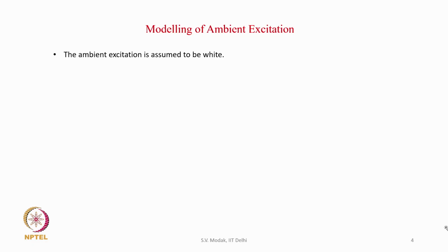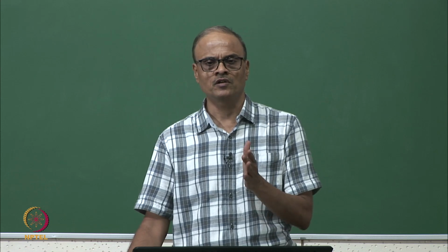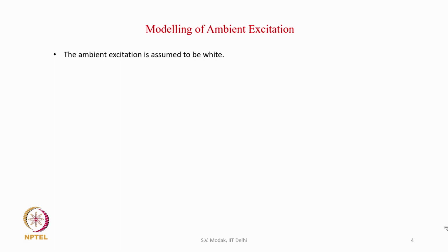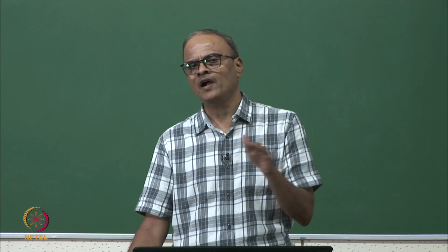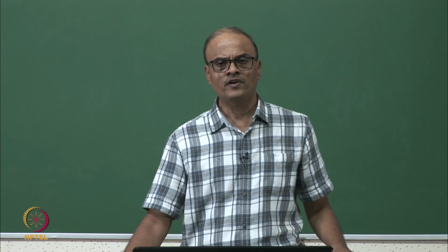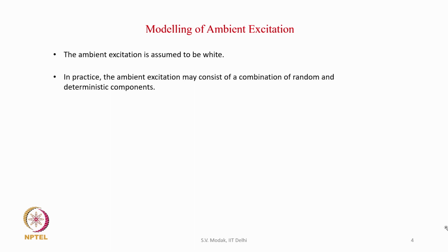The ambient excitation is assumed to be white in operational analysis. So, operational analysis assumes that the random excitation which is acting on the structures, the natural excitation, is white, and we know that the white signal has power spectral density which is flat over the whole frequency range. So, it excites the whole frequency range. However, in practice the ambient excitation may consist of a combination of random and deterministic components.